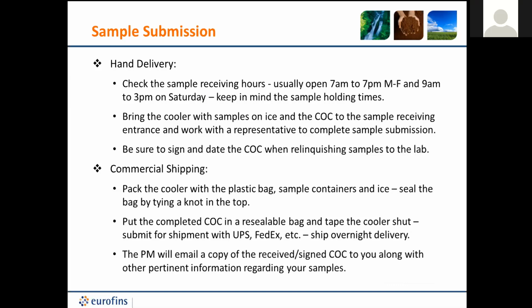Well, I mean, for certain constituents that have a short hold time, I'd imagine they'd want them to get dropped off right away. But for the standard 3, you know, the pH, oil and grease, and 12% solids, and since pH is going to be done in the field anyway, is it really that critical to have them there immediately after a rain, or they can pick it up within a reasonable amount of time?